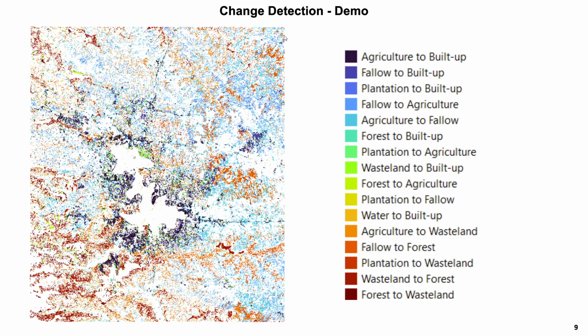land use. And this change detection will be affected severely by your classification accuracy. If there are a lot of mixed pixels and the accuracy of the classification is low, it will be directly propagated into the change detection also. It will give you unreliable results. Say your built up area has converted into a water body. This is a very unrealistic change.